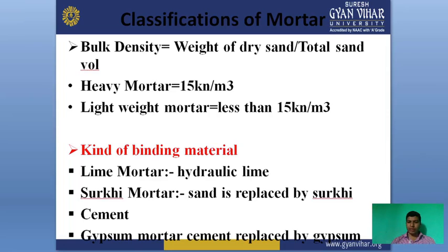In the pounding method, lime and sand are mixed in a dry state, and the mixture is placed into pits, and then water is added to the mixture while repeatedly turning it up and down. It means the required amount of water is added at equal intervals. When the mortar mass becomes continuous, it is taken out of the pits to be used in masonry work.